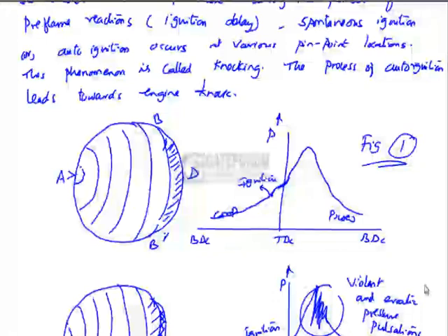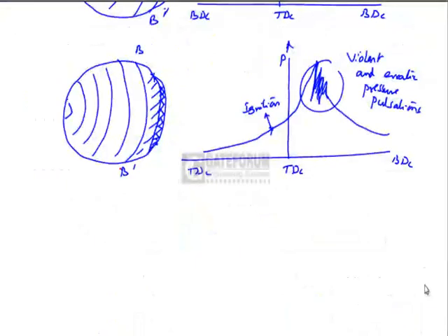In figure 2, it is assumed that when the flame has reached the point B', the charge ahead of it has reached the critical auto-ignition temperature. During the pre-flame reaction period, if the flame front could move from B' to only C', then the charge ahead of C' would auto-ignite.